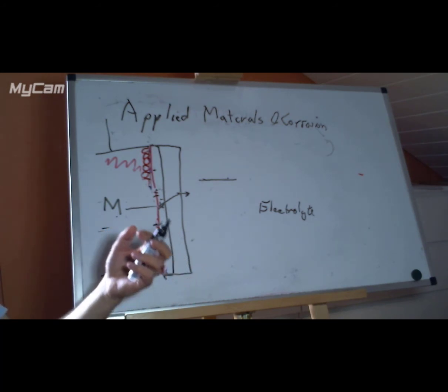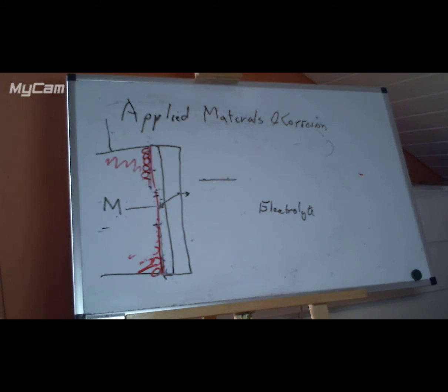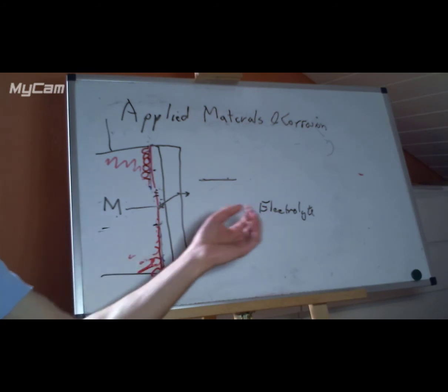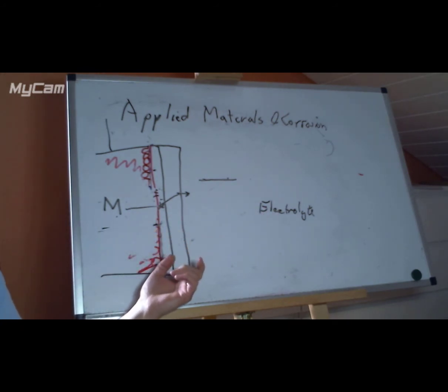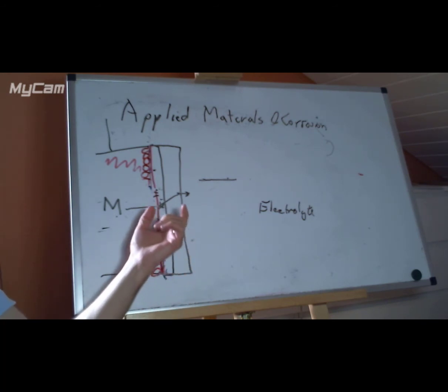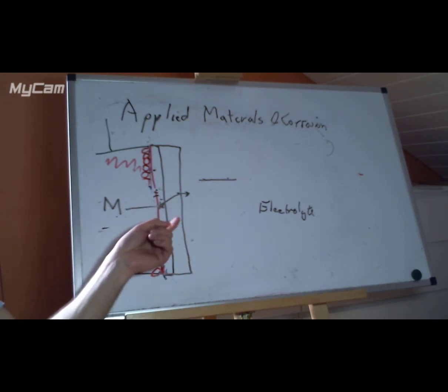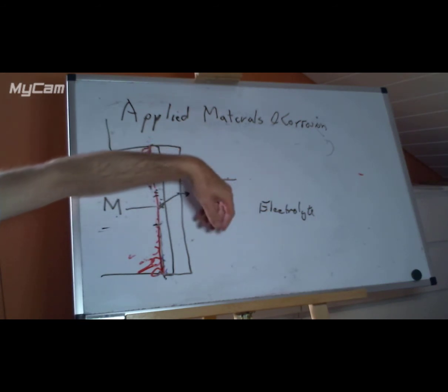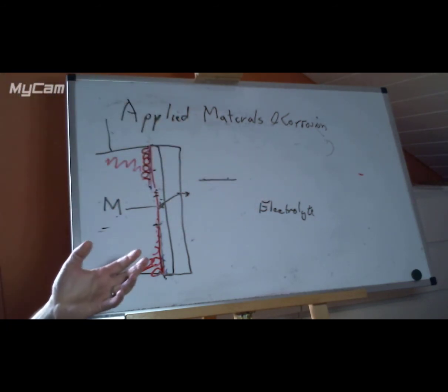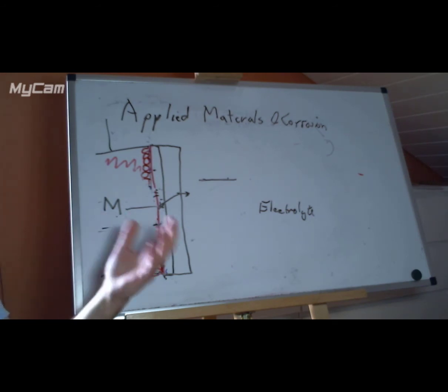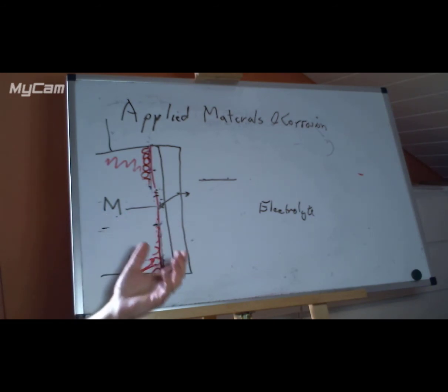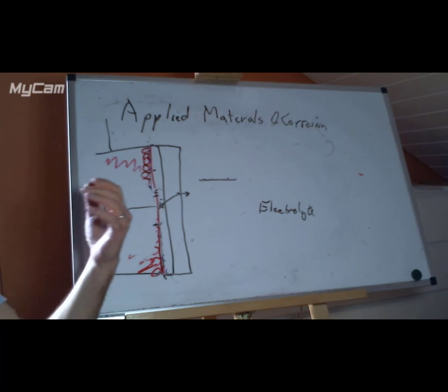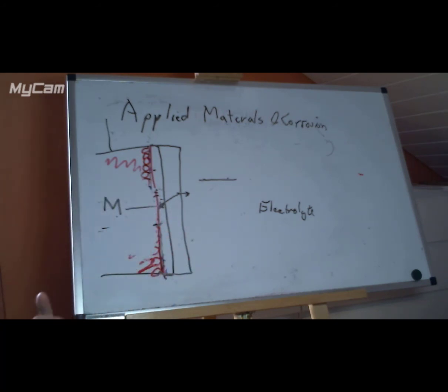It's a dynamic equilibrium. It's also not even a proper dynamic equilibrium because the metal is continually ending up in the electrolyte, but the thickness of the oxide layer appears to be constant because the thickness is coming from the back effectively and the dissolution is going out to the front. In this case, we can still see a stable state, a steady state, but it's not a permanent steady state, and this is what we typically aim for on our Pourbaix diagram, which brings us back in a circle to the diagram that we had before.